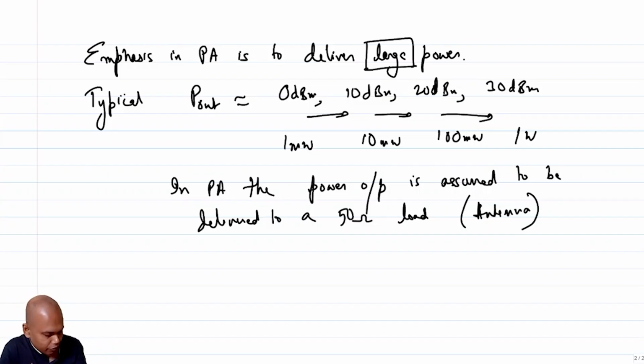And even if you design a perfectly balanced antenna which gives you 50 ohm, and you deploy that antenna in the field, then the moment the antenna radiates something, if there is a blocking surface nearby, or some car goes ahead and cuts through the line of sight through which the antenna is propagating, there will be a reflection from the interface. The moment you have a reflection from the interface, from transmission line theory, we understand that the impedance is no longer 50 ohm. There can be deviations, so you can have imaginary components also.